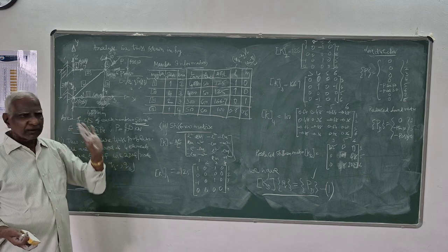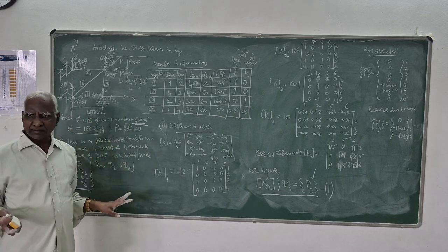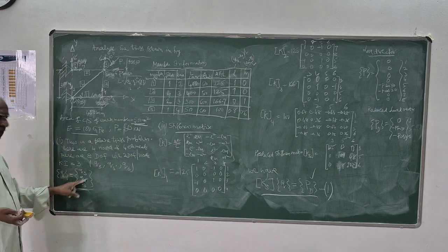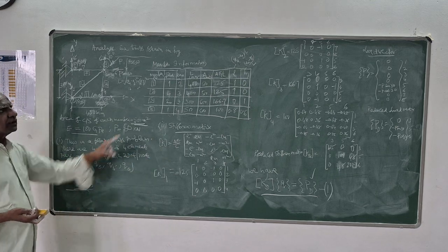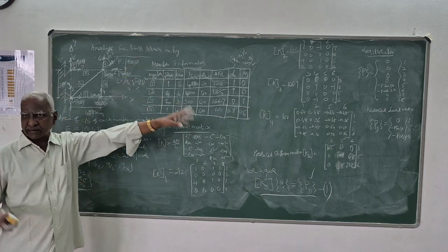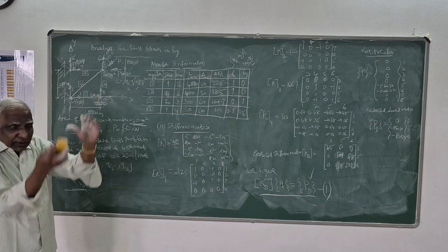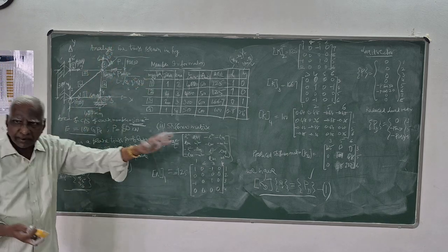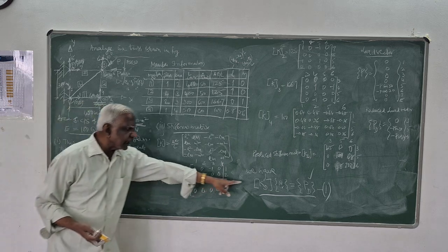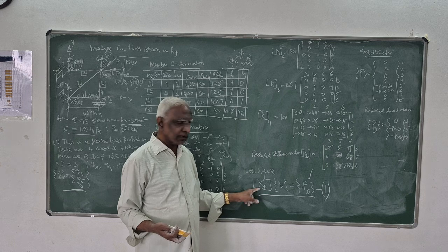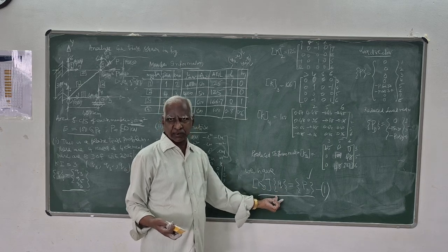Is it clear now? This much information is there. Analysis means only this. First, we have to find out the kinematic indeterminacy. Then we develop the entire structure stiffness matrix and from that the reduced stiffness matrix. Similarly, all known vectors, the reduced load vector. Then take only that reduced load vector and reduced stiffness matrix, and find the unknown displacements.